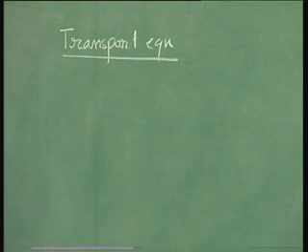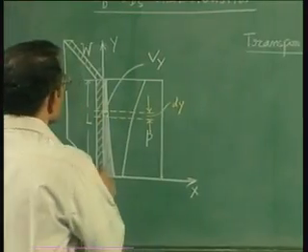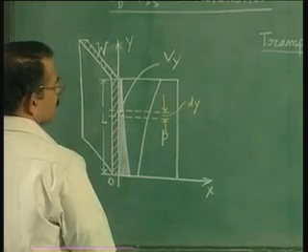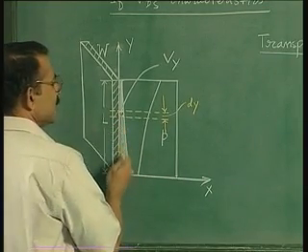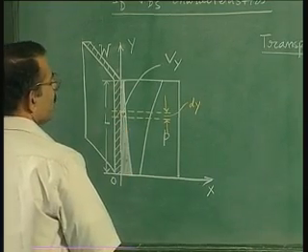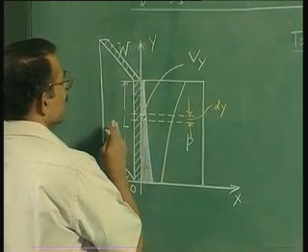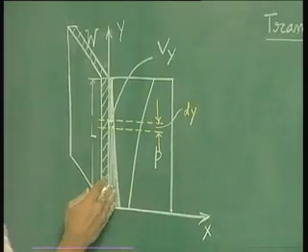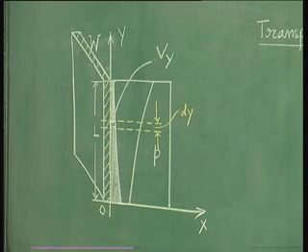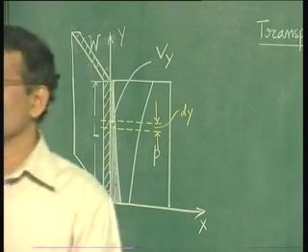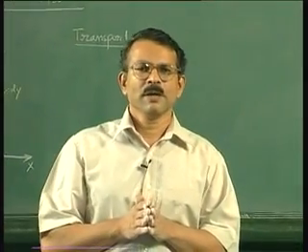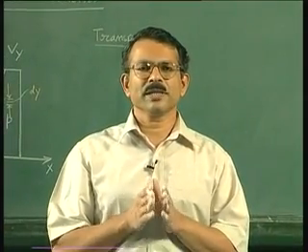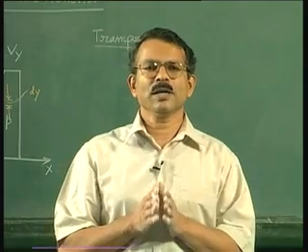We shall neglect the current because of diffusion. Please note, why can there be a current because of diffusion? Because your electron concentration is changing from source to drain. Therefore obviously there is a tendency for diffusion, but when your gate to bulk voltage is more than threshold voltage and this region is strongly inverted, it can be shown that the drift current dominates over the diffusion current. Therefore, your transport equation further simplifies to only electron drift.